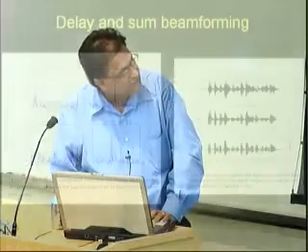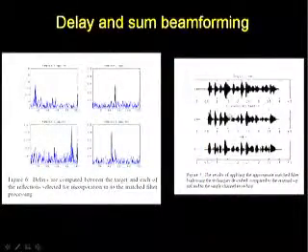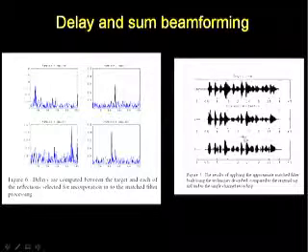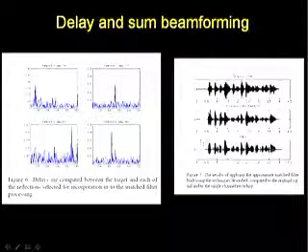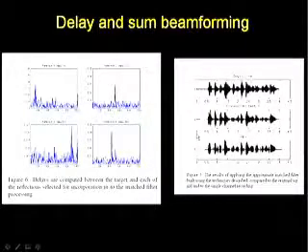For performing delay and sum beamforming, we need to figure out the delay between the reflected image sources. Here is the single channel source after doing the approximate matched filter process, and this is the original. We get significant improvement, at least in perceptual quality, but we need to run some more tests to give you quantitative, say PESQ scores or something like that, to tell you how much improvement we've had.